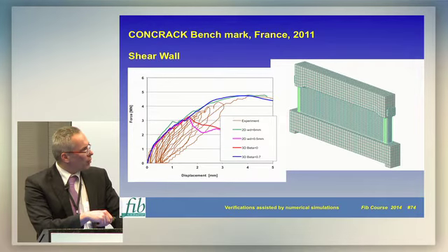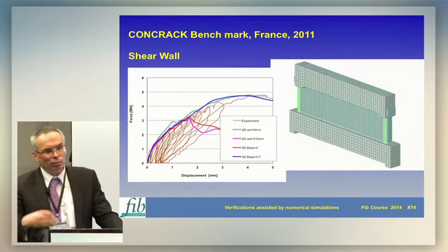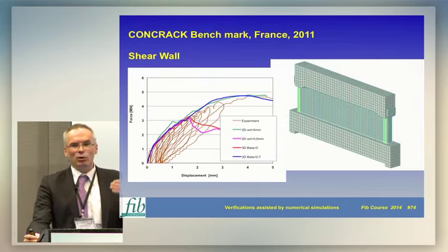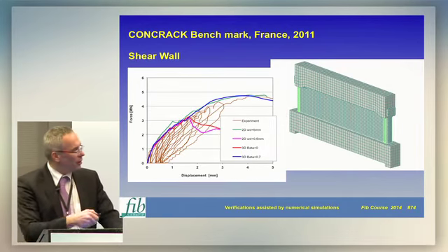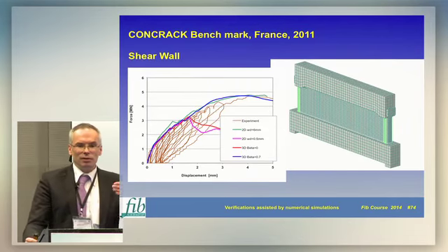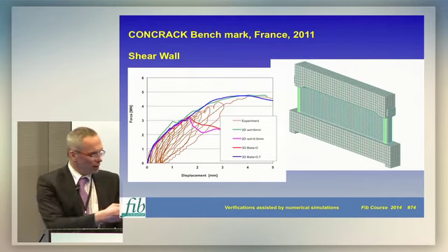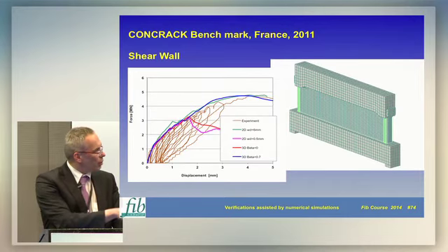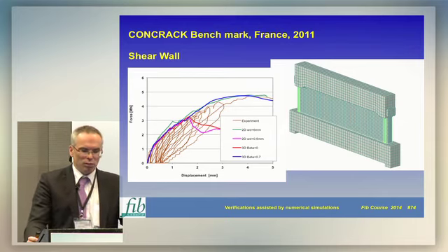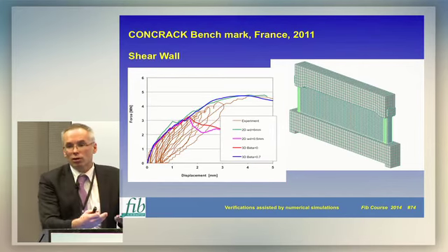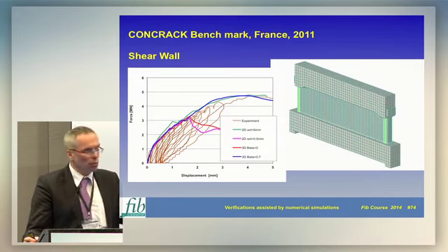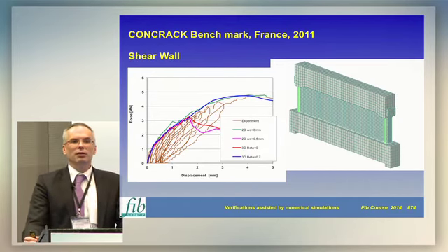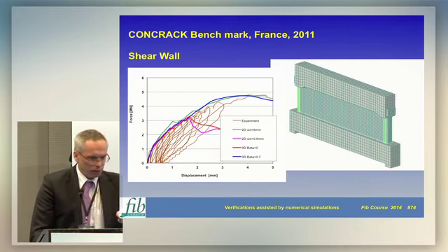But of course, again, if we use the default settings which are in our program to make sure that the engineers get behavior on the safe side, and these behaviors little bit underestimate the ductility of the compression failure, then you obtain lower peaks. So for 2D, it is quite natural that to have a 2D model of the confinement region, it really needs to be in the model. It cannot be calculated automatically. But the 3D models should capture the confinement of this crushing region.